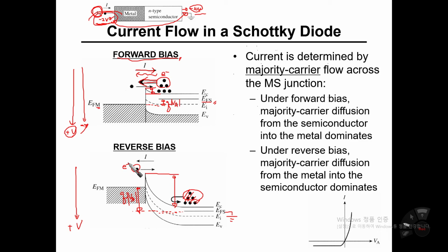Yes, the electrons which have a slightly higher energy level beyond the Schottky barrier height. Only those electrons can move toward the semiconductor, so the current flowing across the MS contact can be defined from semiconductor to metal side.